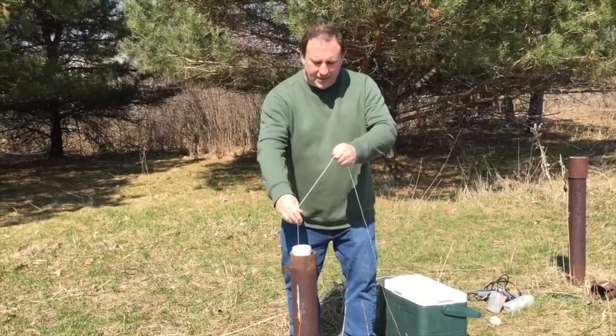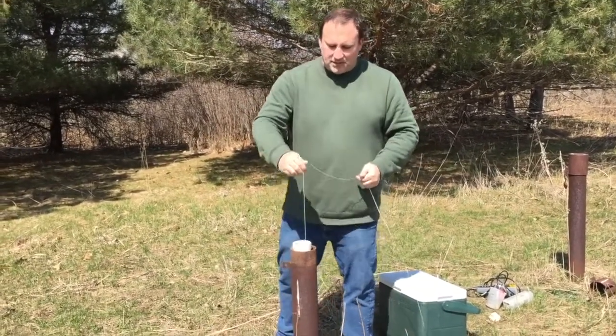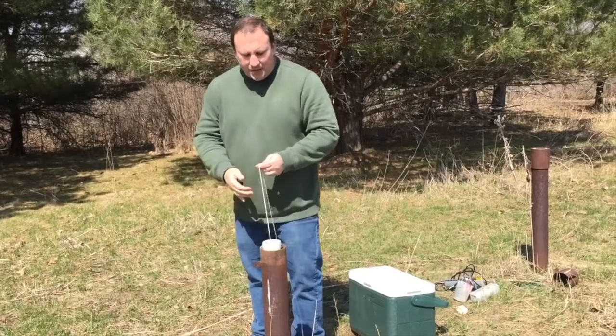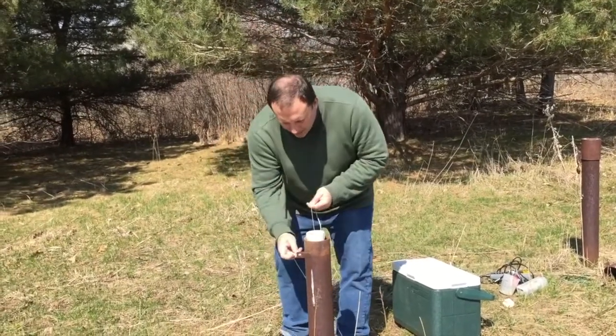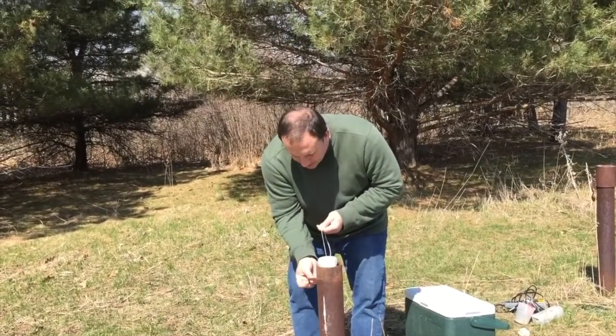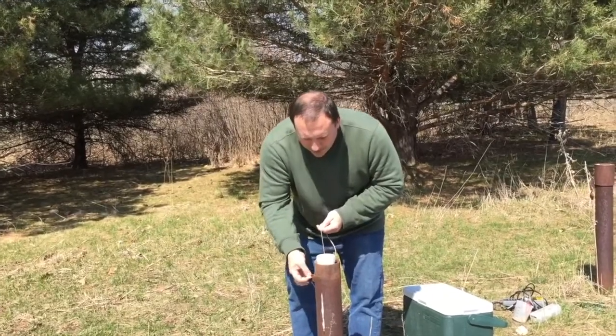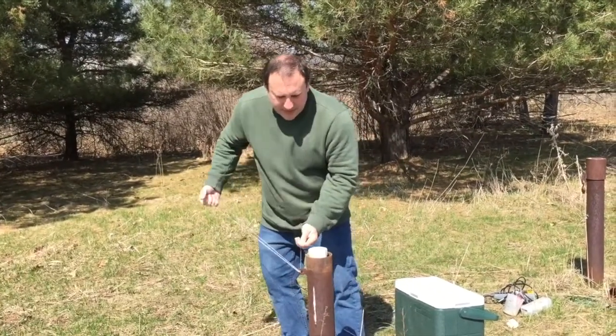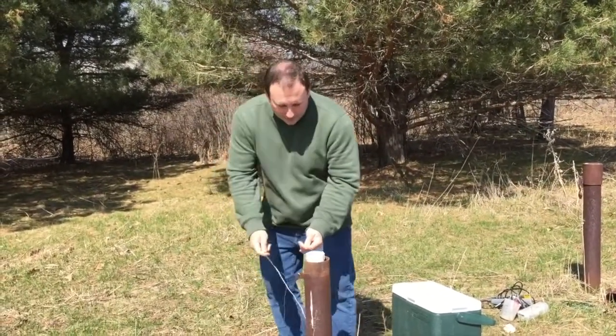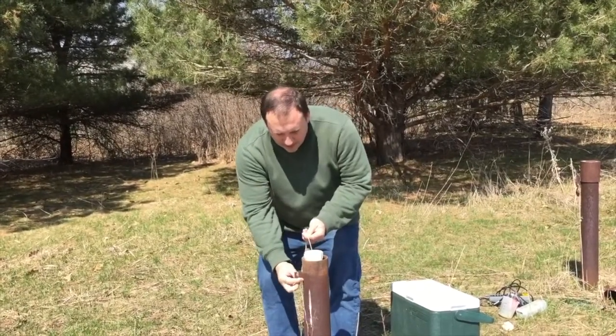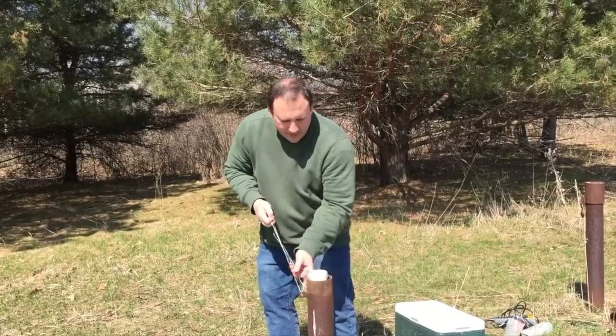Oh, I already feel it. It's hit the bottom. So that's 45 feet or so. So I can pull that up a few feet. And now what I can do is tie this thing on here. It doesn't matter exactly what the depth is that it's tied on, because I know the static water level. So that to me is going to be an adequate process. Okay.